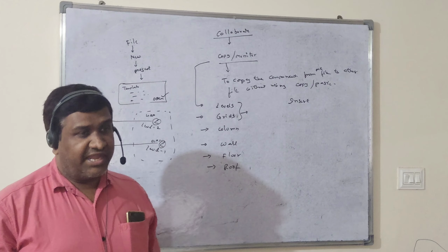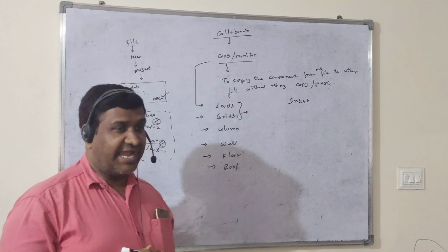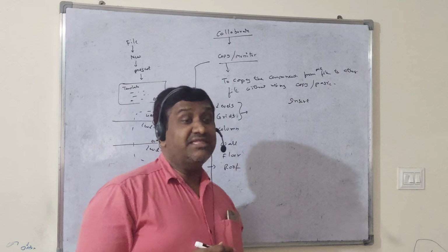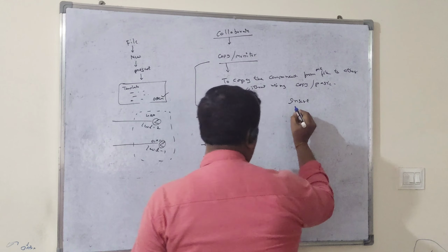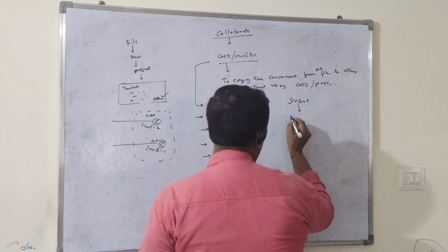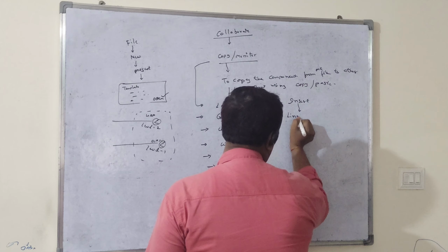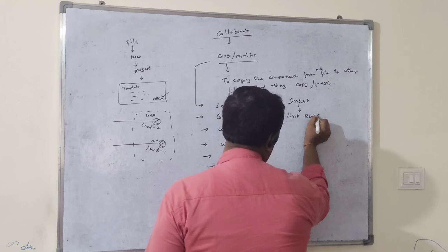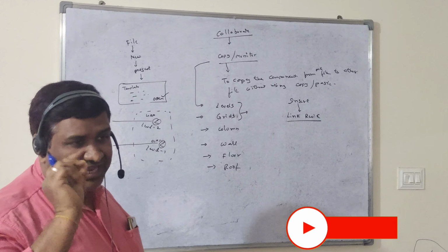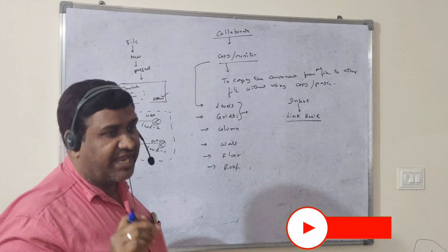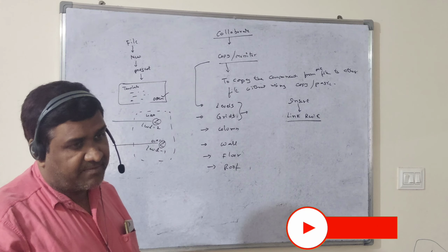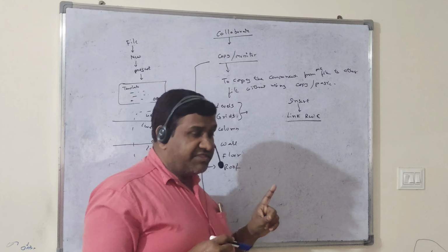Yes. Beside Insert you will find one more menu, Annotate. Am I right? So you have to go with the Insert menu. If you click the Insert menu, a number of ribbon menus will appear. In the ribbon, the first menu is Link Revit. Have you seen that menu? Link Revit, Link CAD, Link IFC, like that. There are a number of menus in the Insert menu bar, and one of them is Link Revit.